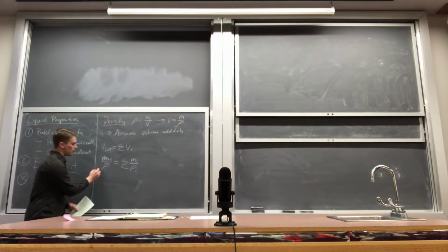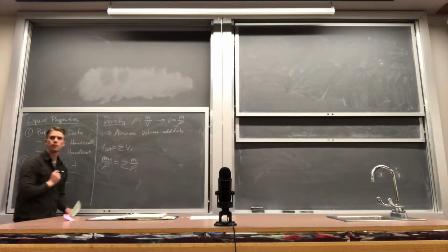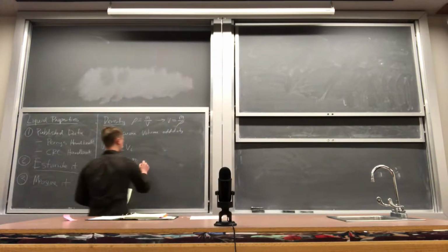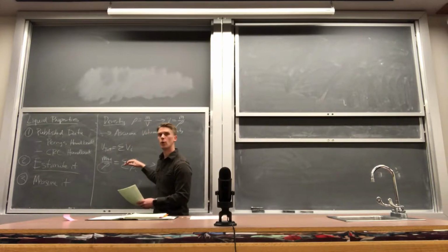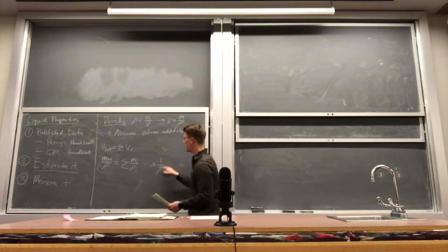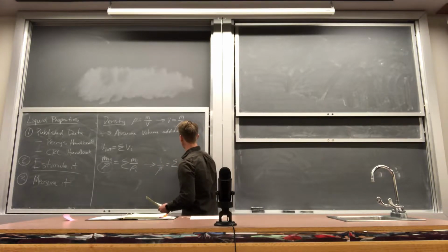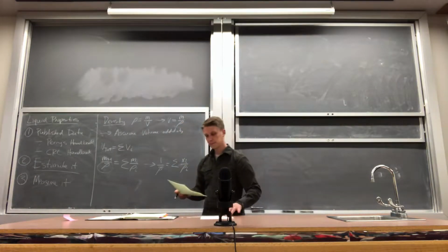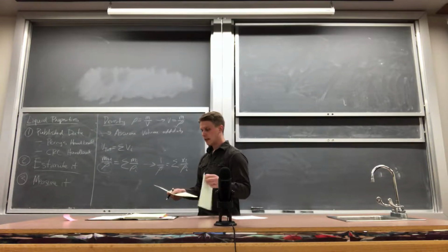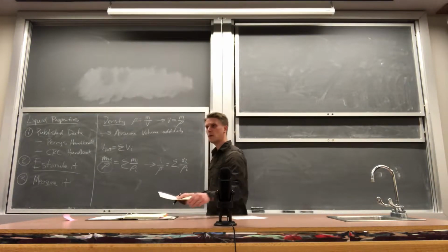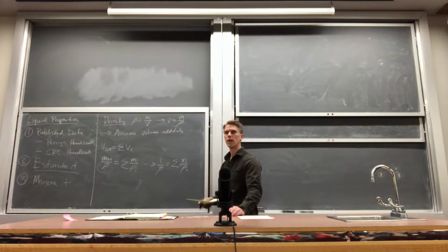So from here, we can calculate the average density of a fluid mixture. Another way we can write this is if we divide both sides by the total mass. We have 1 over the density, the average density, is equal to the summation of the mass fraction of each individual component divided by the density of their individual components. This is not the most accurate way, but it is a way that it'll get you 90% of the way there for the most part.